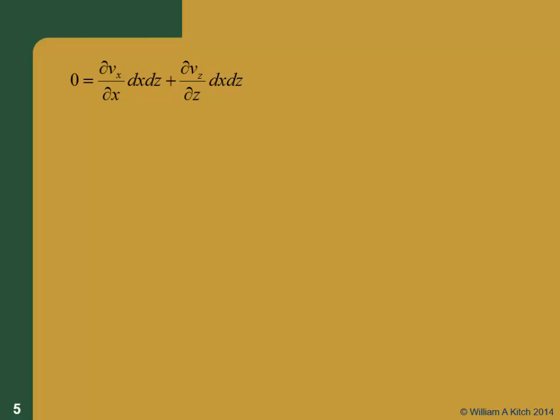So now we're going to apply Darcy's law. All right? Oh, I'm sorry, I'm going to simplify this first by dividing by dz. Sorry about that. Don't tell the mathematicians that we did this, but we're going to divide by dz and dx. Now we're going to apply Darcy's law. Darcy's law is that Q equals KIA, or the velocity is equal to minus K times i.